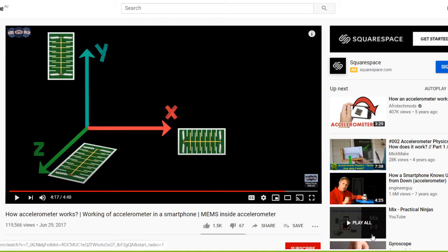Having such multiple MEMS systems in different planes, that is x, y and z, that's why I call this a tri-axis accelerometer. So this has three axes. They have three accelerometers, so they can build an orthogonal 3D coordinate system to measure the acceleration. That means for any direction you can fully measure. No matter which side the direction is, you can measure. So this is called complete measurement of acceleration. Sometimes they only have a one-axis or two-axis accelerometer, so they are not complete.